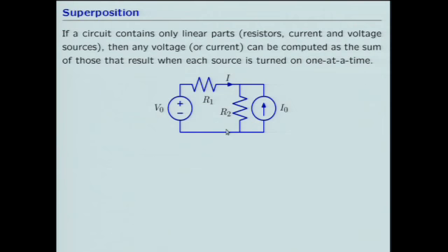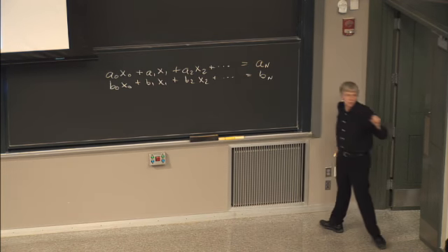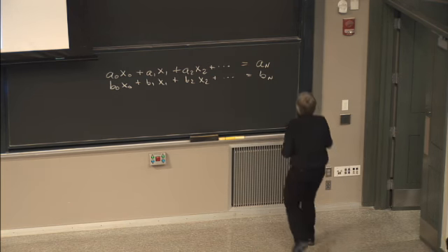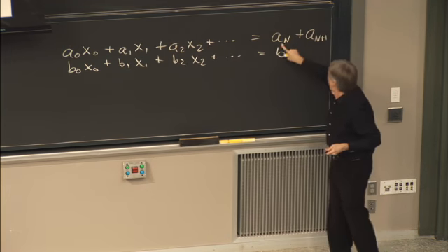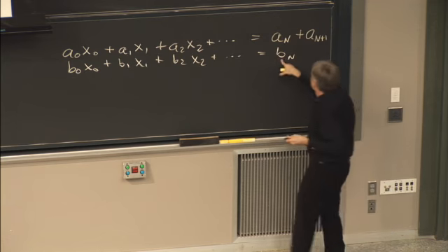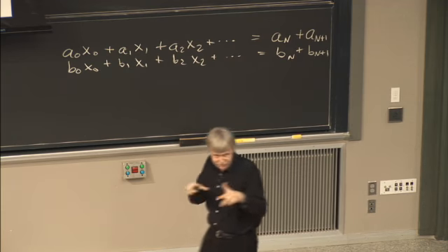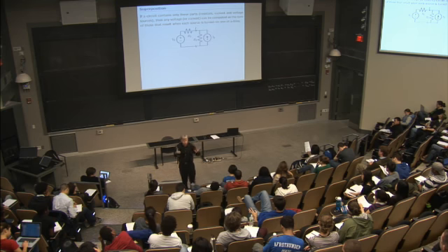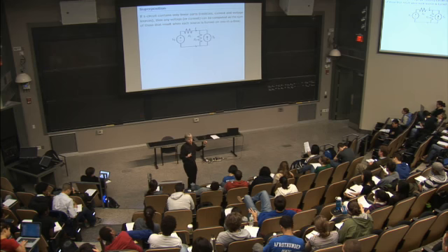You can see that over here. If I had multiple sources, the system of equations that I get wouldn't look quite like this. These constant terms are the ones that come from the drives, the voltage sources, the current sources. So if I had 2 drives, I would get something else here. I would get plus A and plus 1, for example. Source 1, source 2. And I would get source 1, source 2. So the idea is that if I have a system that has multiple sources, I know from the structure of the linear equations that it's just more constant terms.